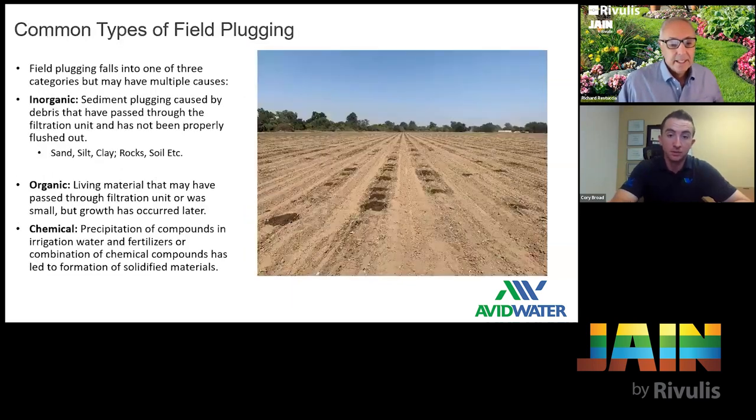Absolutely. So kind of talking about field plugging, I think it generally falls into 3 categories. Inorganic: sediment plugging caused by debris that's passed through the filtration unit. Hopefully you have a filtration unit; I've seen some fields that don't. But again, think of your sand, silts, clays, even rocks, soil. There's a number of different things that can get in there. For lack of better words, dirt. That happens. It probably is more common from surface water applications, but it's there.